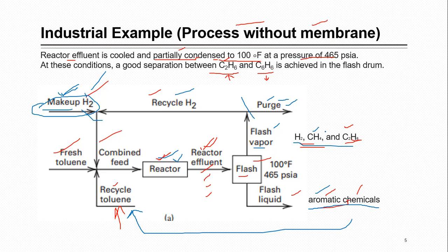Definitely you will be just wasting your heat to heat these chemicals as well. When you are going for cooling, here you will be just cooling them, there is no advantage to you, and then flashing and overall this will be taking place. So in order to avoid this problem, they just purge some amount. Purge means some amount of this gas or vapor leaving from this system is taken away in order to avoid this buildup of these non-usable chemicals inside the system.